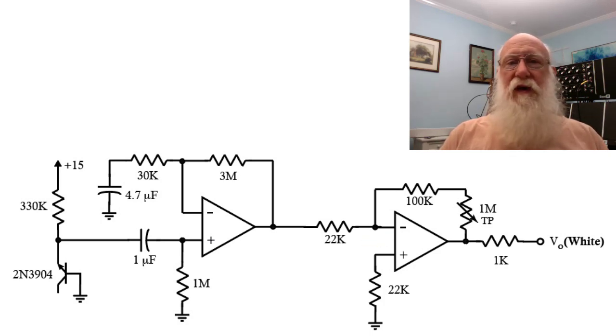Your ear won't detect that, and it probably won't generate any problems in other circuitry unless you've got a really big gain. However, since we will be feeding this into some filters with fairly high gain, we need to get rid of that little DC offset generated in this second stage.